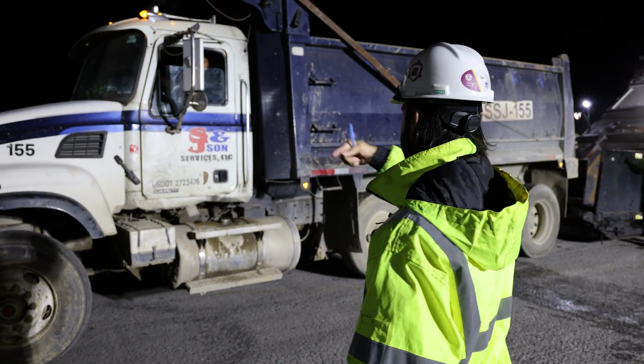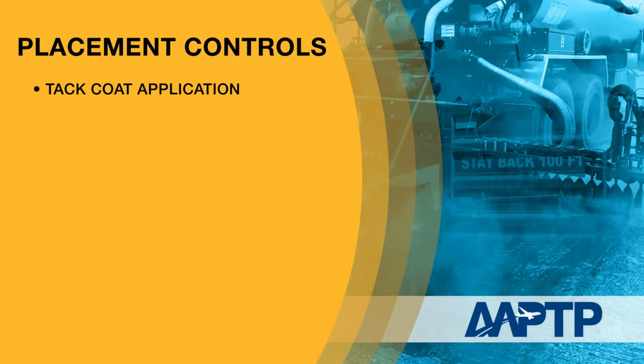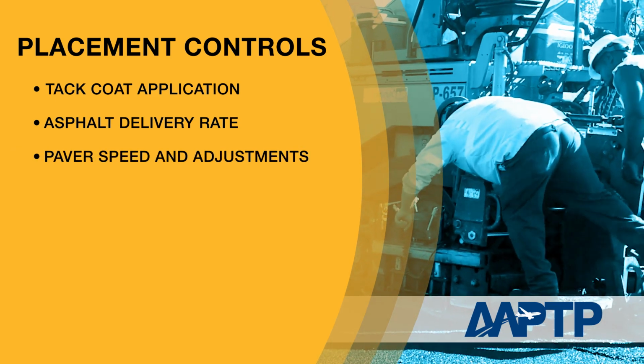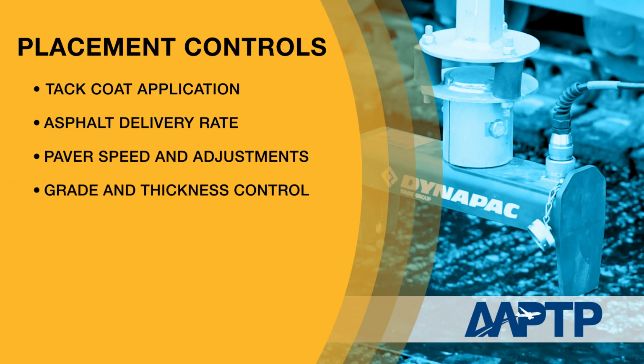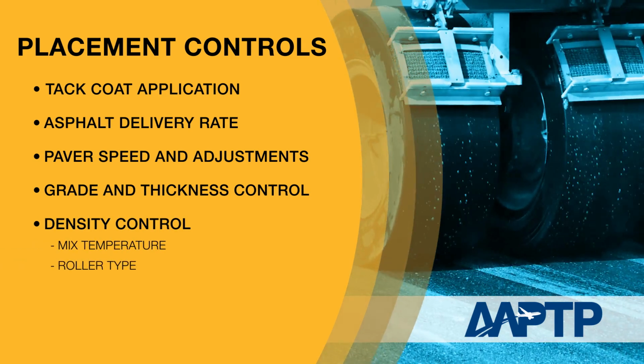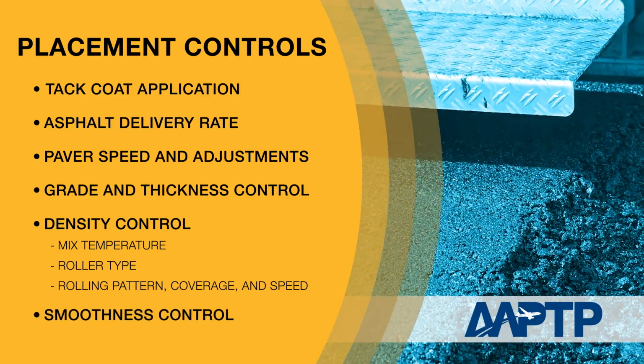The contractor must closely monitor these placement controls: tack coat application, asphalt delivery rate, paver speed and adjustments, grade and thickness control, density control including mix temperature, roller type, rolling pattern, coverage, and speed, and smoothness control.